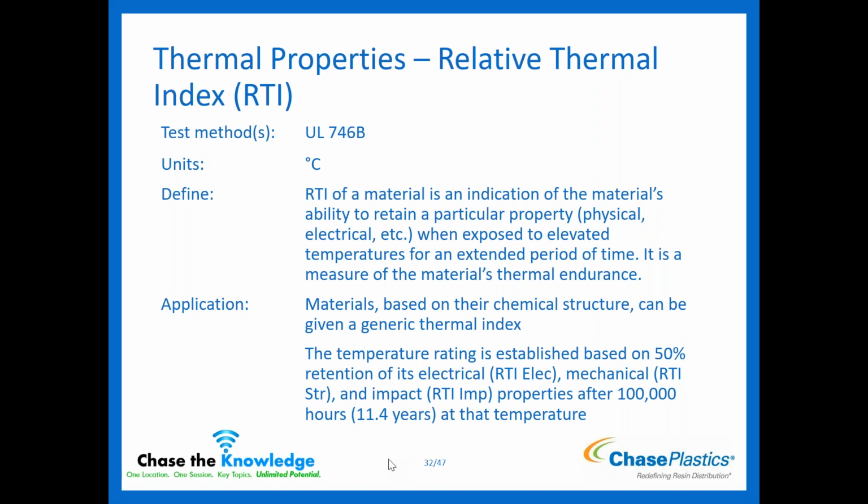And so what does that mean and what does long time mean? The temperature rating given, if we're looking at the Ultem, we're looking at values of 170 C across the board. It means that for 100,000 hours, or 11.4 years if you want to do the quick math, at that temperature, when I test before I expose it, I test the electrical properties, the impact properties, and the strength properties. I can leave that material at the 170 C for 11.4 years, and when I test it at the end of it, it's still going to maintain at least 50% of those values. So whatever the starting value was, put at that temperature for that extended period of time, it's going to be at least half that at the end of it.